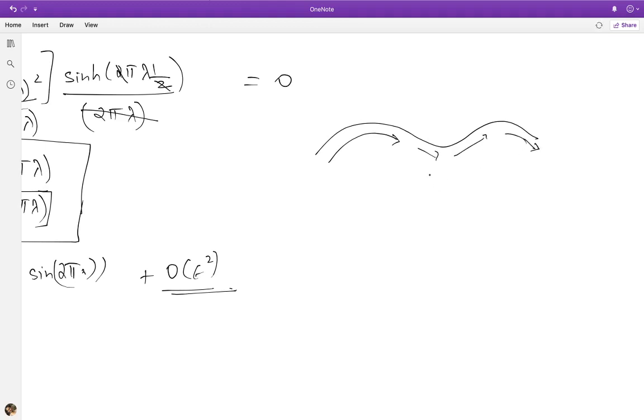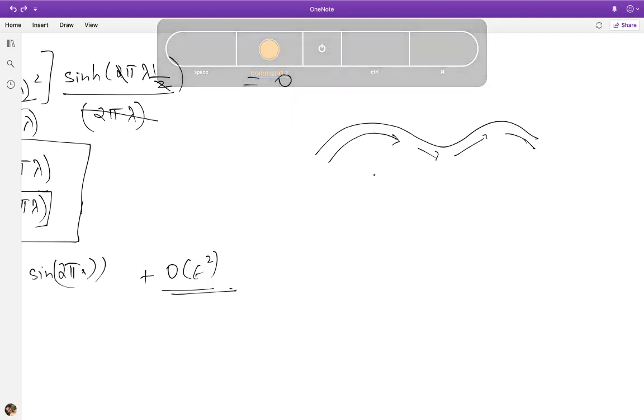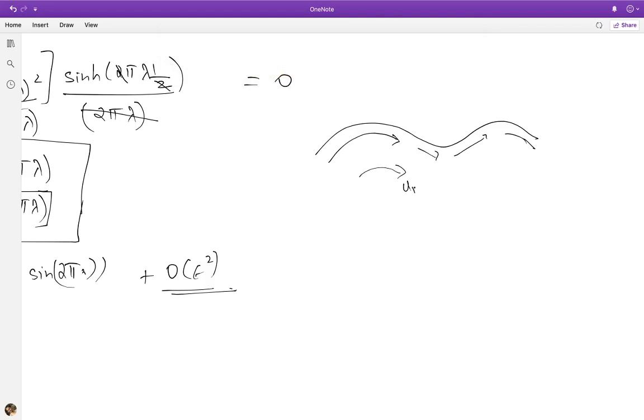For positive epsilon, as the fluid is moving into the wall, I should find that u1 is greater than 0, but v1 will be less than 0. Similarly, when the fluid goes into the diverging sections, I'd expect the fluid to decelerate relative to the base state solution, so u1 should be negative, whereas v1 will be positive as the fluid moves upward.